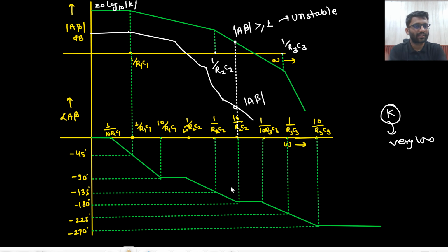That's why we go to cascode amplifiers, all these kinds of amplifiers. There we are not just cascading; by using the current source, we are somehow increasing the gain. Otherwise, why would you need cascode amplifiers? You would just keep on cascading the stages. But if you keep on cascading the stages, there is very high chance that your circuit can go into instability in case of negative feedback. So that's why we cannot keep on cascading. We need to use cascode or some other technique.